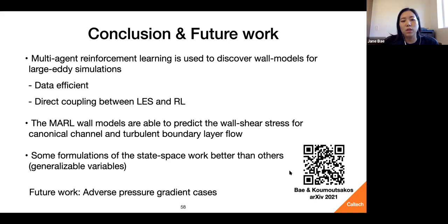So one is actually applying the wall shear stress that we've obtained from the wall model as a boundary condition, and that's where the slip boundary condition and the Neumann type boundary condition work. And then there's the part where we try to obtain the wall shear stress. In the traditional wall models that I mentioned, the algebraic wall model and the RANS-based wall model, they basically solve that ODE or equation close to the wall to obtain that wall shear stress.